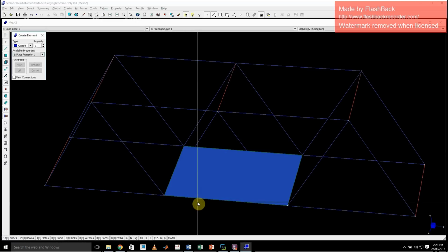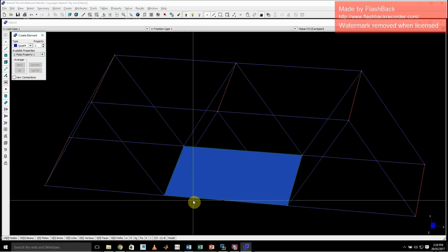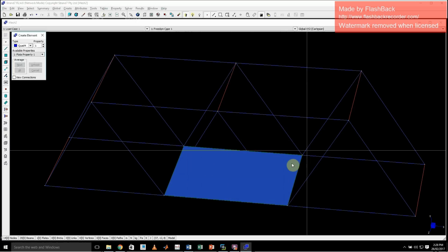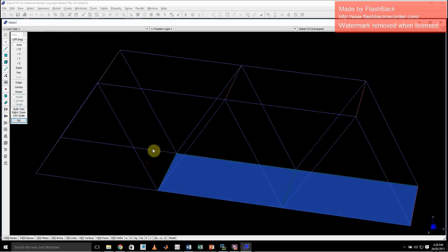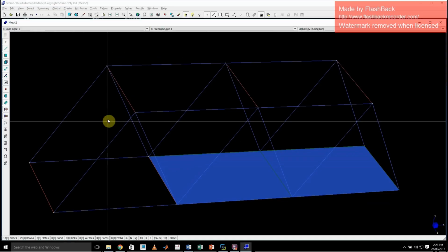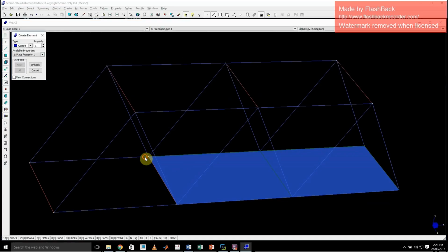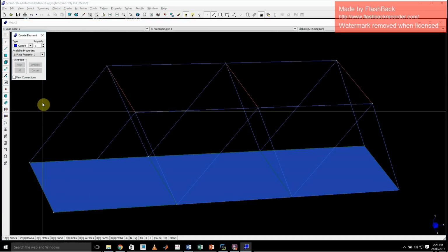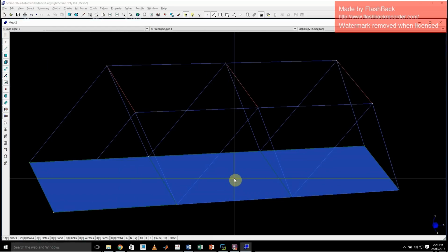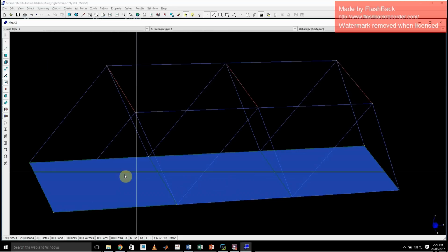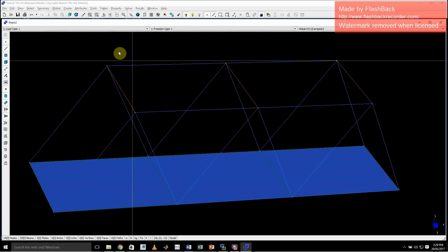Why is this relevant? Well, because considering this thing is a bridge, it probably doesn't just have a few beams across. It probably has plates in here. Yep, that's definitely connected to the wrong spot. Probably has plates in here to operate as the road. If you did have a road like this, you might not really think that point forces are the correct way to apply your loads. You might want to say that in reality what we have is something much more similar to a pressure on these plates.